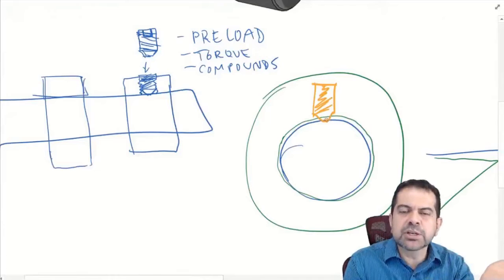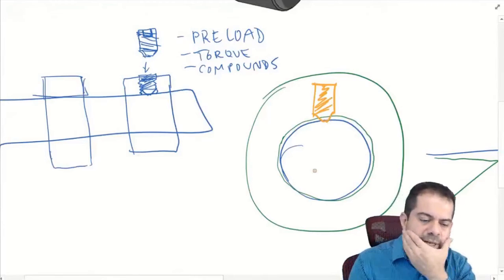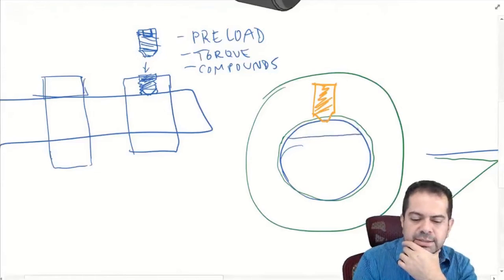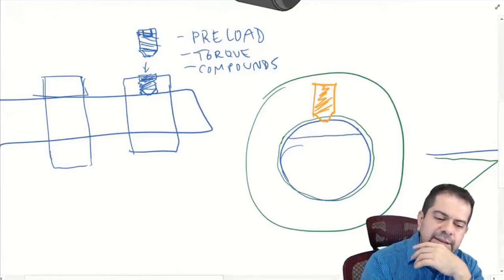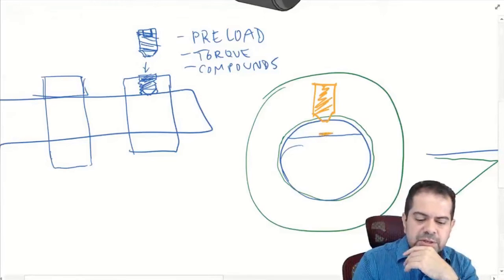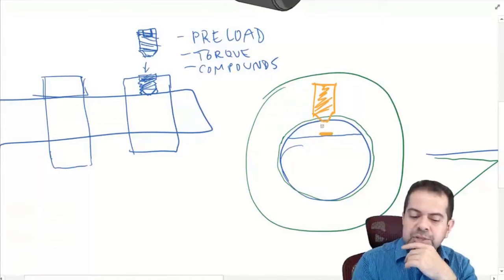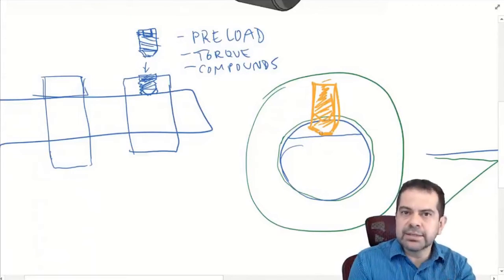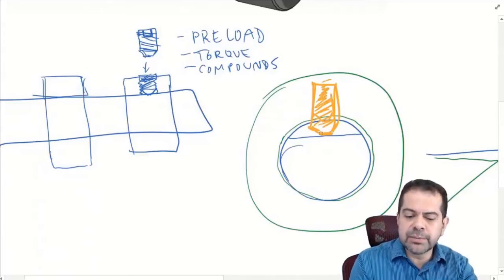on an outside curved surface. So that's why you see pretty often on motor shafts, you will see a flat. If we have a flat, now the set screw, especially, you remember they're flat tipped set screws. The tip of the set screw can engage the flat on the shaft, and that's a better design all around. Now you have a flat against a flat. It's harder for the shaft to rotate in relation to the collar.